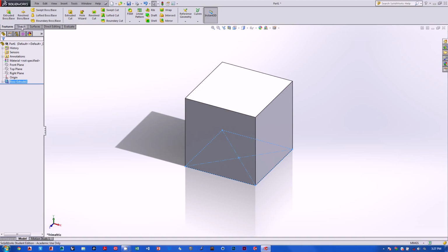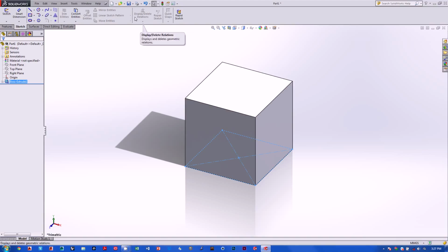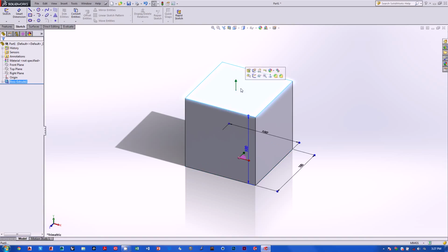Moving forward, we're also going to be using the Sketch tab. This is something most everybody should be familiar with, but as advanced users, we're going to be playing around a lot more with this button here, Convert Entities. Convert Entities is a really valuable tool, which, if you haven't messed with it yet, allows you to take, say, the surface or the edges of a model that you've built and transform them into usable line work that you can then build off of.